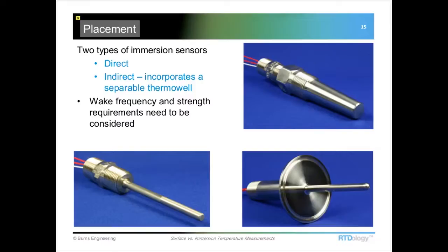A lot of it would depend on the type of measurement you're trying to make. The thin film works well if you're looking for the fastest response time from an RTD. The wire wound version is going to give you a more stable, repeatable measurement over a long period of time than a thin film will. It's a very small difference in relation to the kind of accuracy that a lot of people want to get out of a surface mount sensor. But it certainly is a bit of a consideration. Okay, thanks.